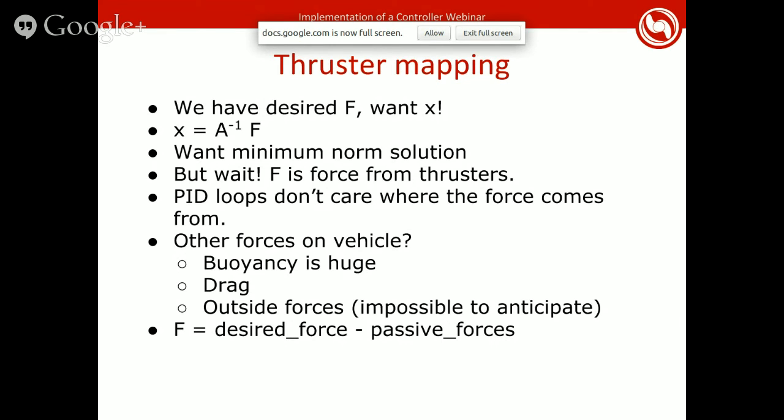You might say, why not just clamp the values at max force? Yeah, that would work, but it's not ideal sometimes, because you might want to have some priority over which degrees of freedom get preference, right? So if your PID loops output things that are crazy, and one wants to go a really high angular acceleration, and the other 3 want to go really fast in one linear direction, it may be a good idea to prioritize torques so that your vehicle has a stable orientation.